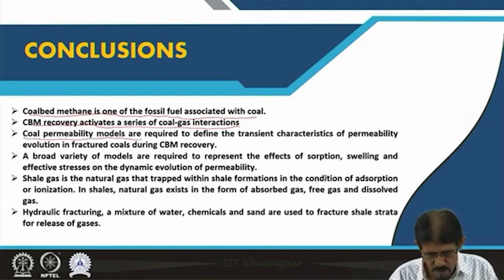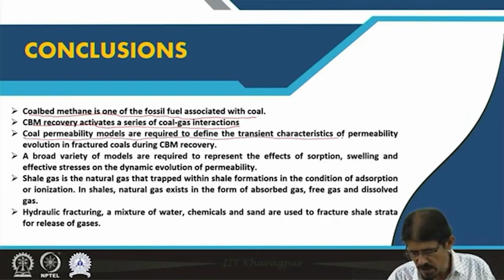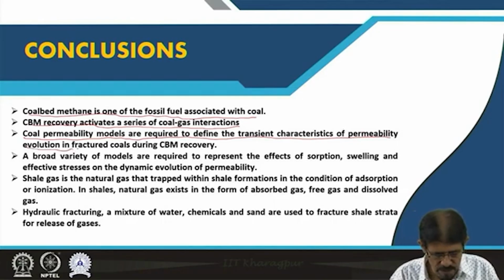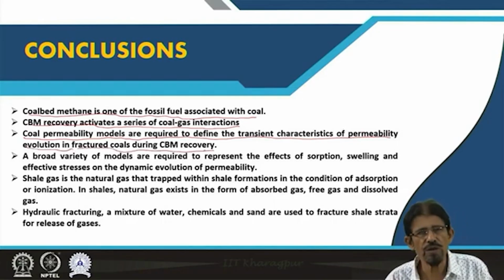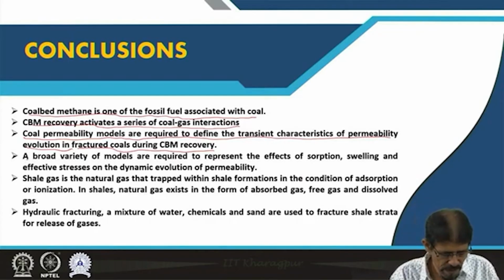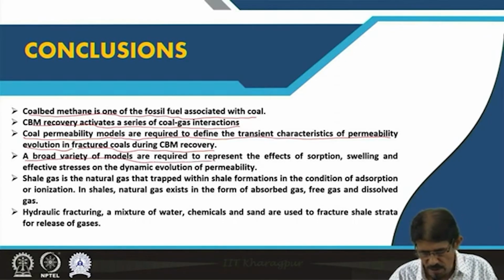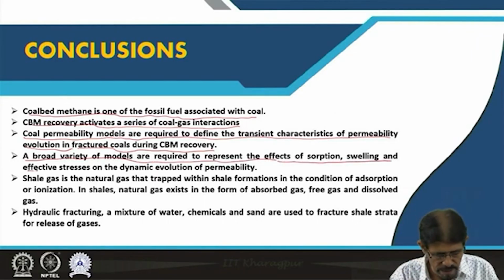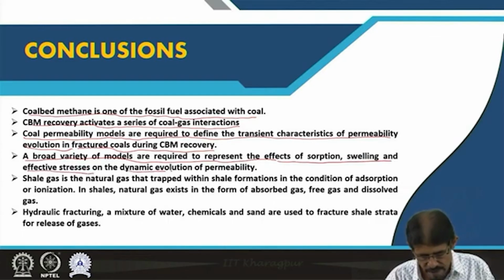Coal permeability models are required to define the transient characteristic of permeability evolution in fractured coal during CBM recovery, and this CBM reservoir has dual porosity and permeability. A broad variety of models are required to represent the effect of sorption, swelling and effective stresses on dynamic evolution of permeability during extraction of CBM.